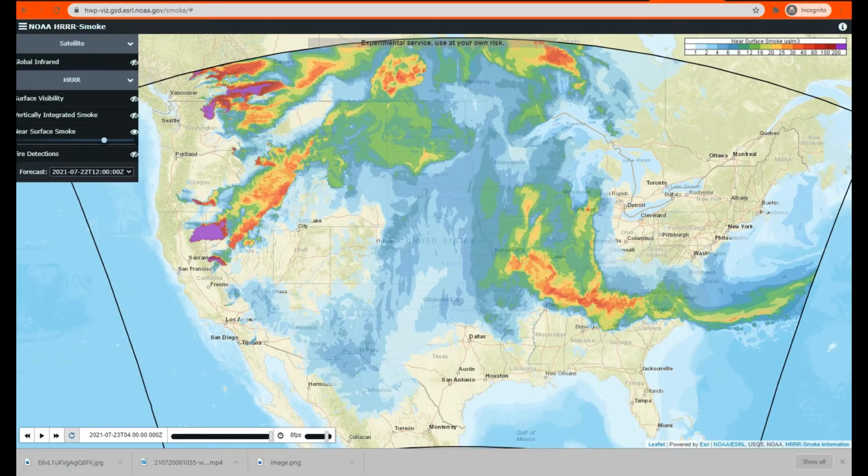So if you have solar panels and you want to see how much energy you should have made, I'll show you one method to do it in this video. The reason to estimate energy production could be to see if there's degradation in an older solar panel array, for example. The first step is to go to the Weather Underground website.